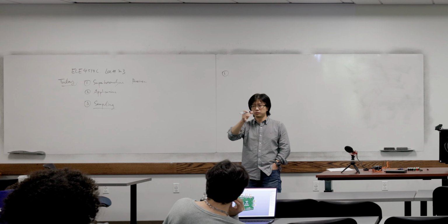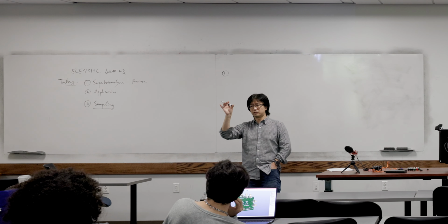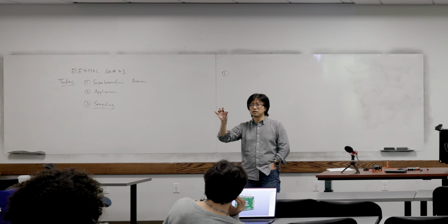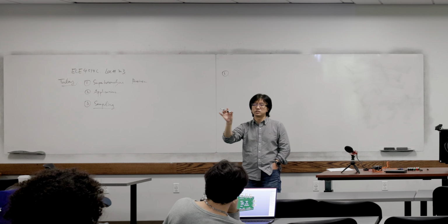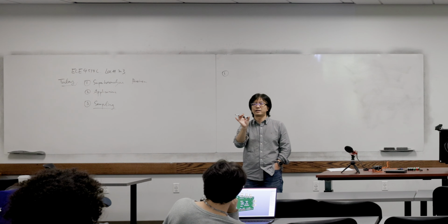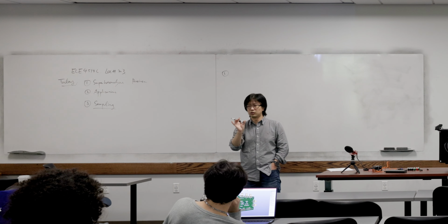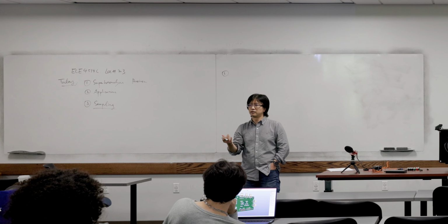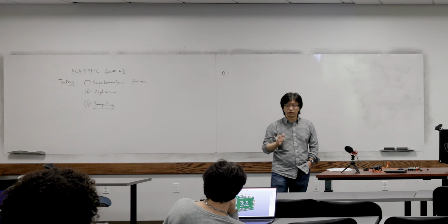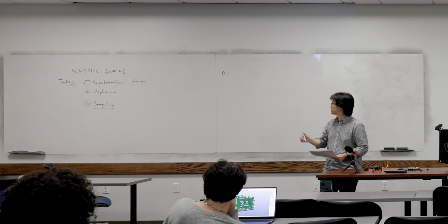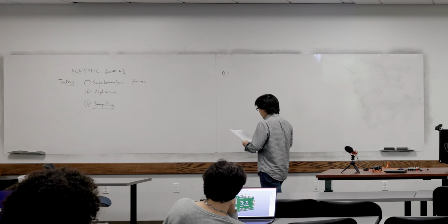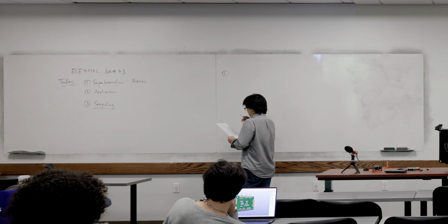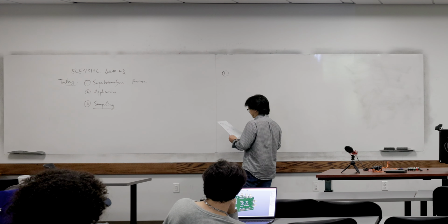And then when we receive the signal, whatever its frequency, we multiply cosine and shift that signal to the certain frequency band, and then we pass that through a bandpass filter on that band, and then we're fine. So let's see whether this simple idea works or not. That's basically the idea. There will be some problems, and we're going to see that later.